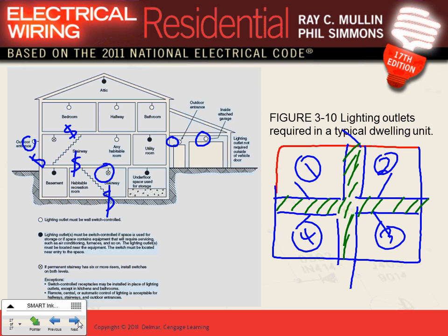So that's very, very clear. That's the only thing I want to mention. If you have an apartment, the common spaces, hallways, anything common, laundry areas, receptacles in common areas, and lights, garage door opener, if it's a door opener for the whole apartment, all these have to be fed from a separate panel other than the tenant's panel. Cool? Everybody's okay with that one? So that's what I want to mention, just in case